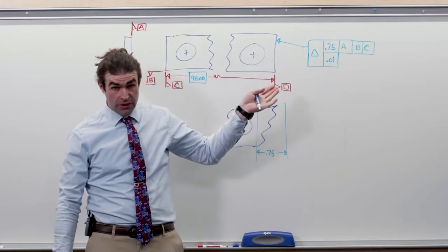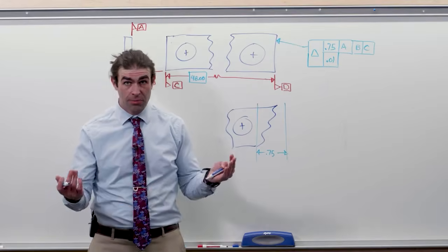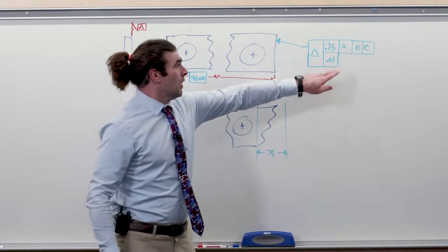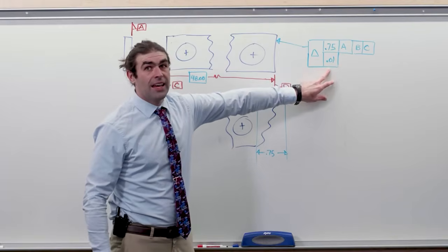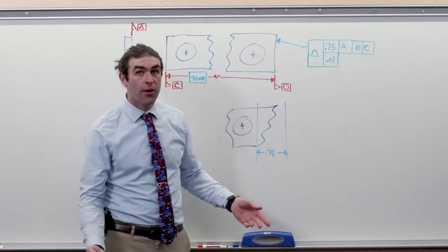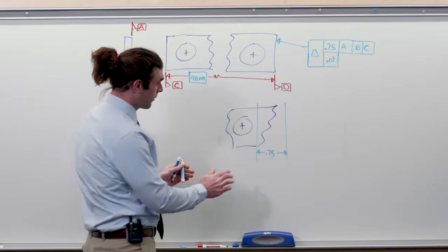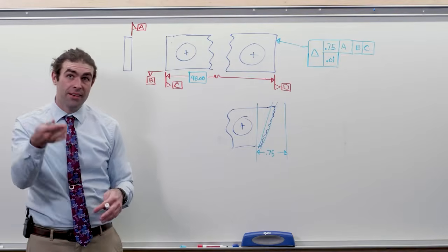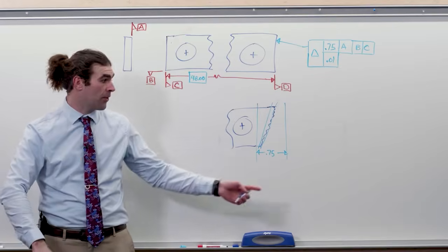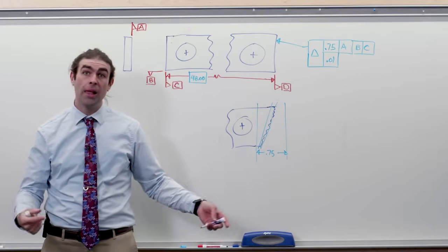Now, in this particular example, 2 single segments means the same thing, but I'll make it composite just to show you the one symbol. Okay, so this 10 thousandths indicates that this surface needs to be flat within 10 thousandths, and it also has to adhere to this upper segment. So what that's going to do to us is flatten that surface up, but it's still free to tilt and move around within this 3/4 inches, and that's exactly what we're looking for there.